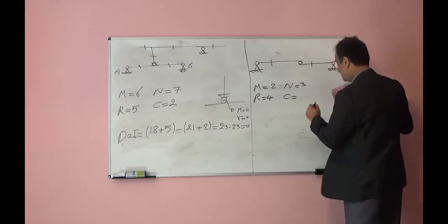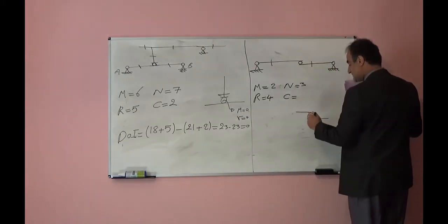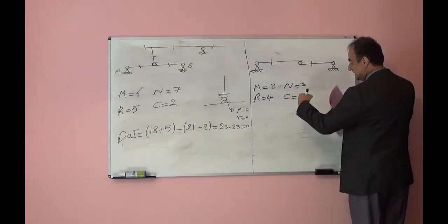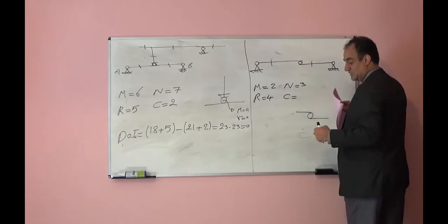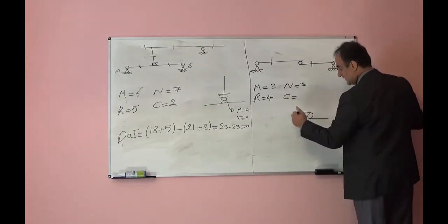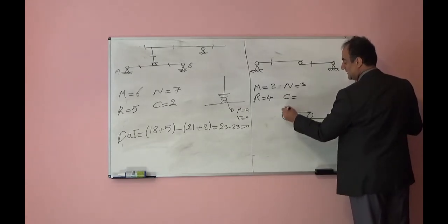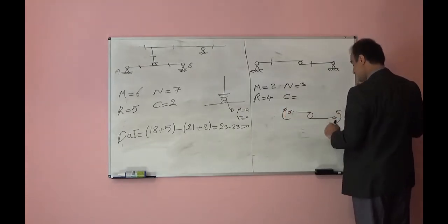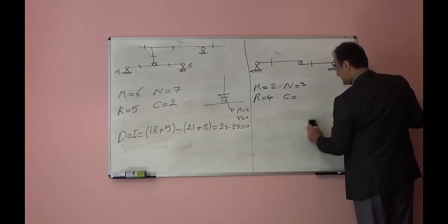It can rotate with respect to each other, and it can move in the horizontal direction. So this system, if we apply axial force, it can move. If we apply moment, it can rotate. So two internal forces are 0.